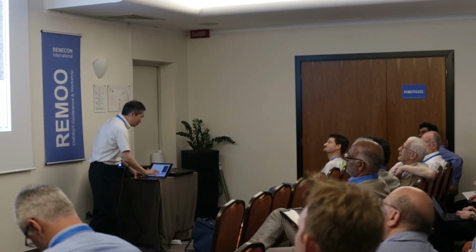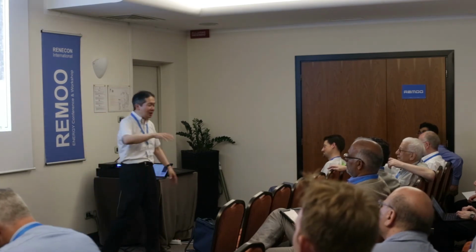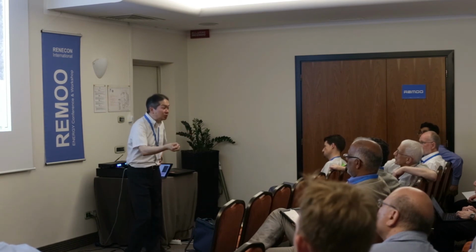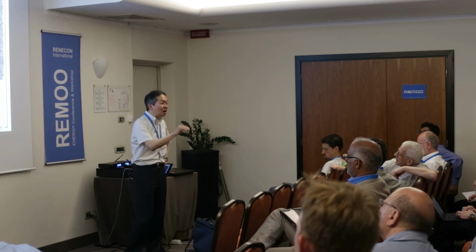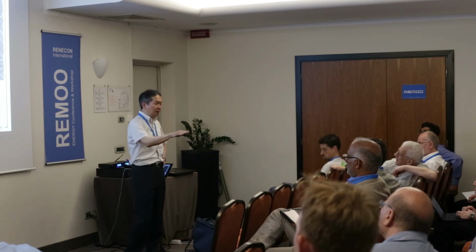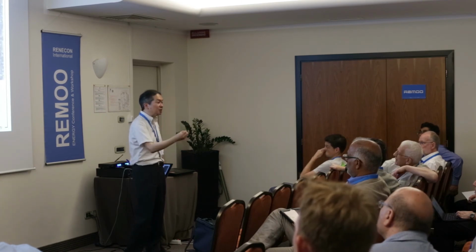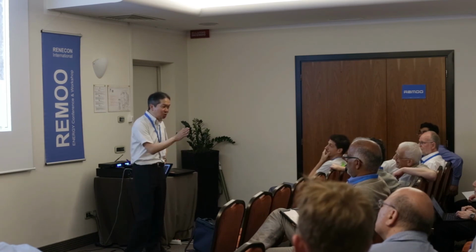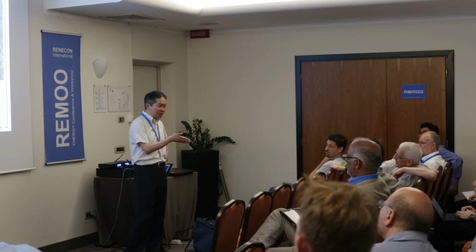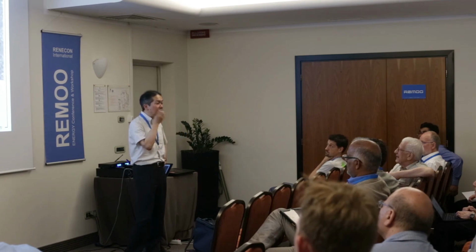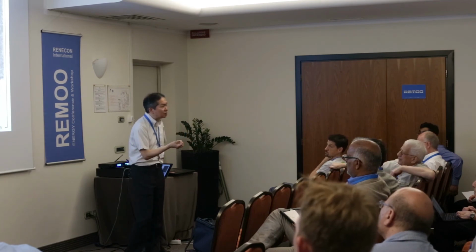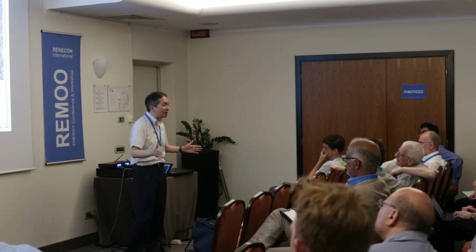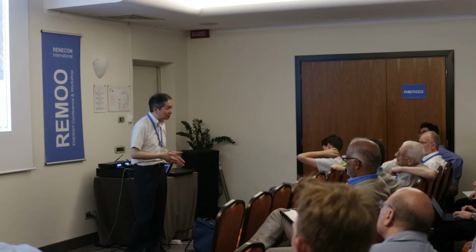It takes some time to go back to that. We don't have time, we'll talk later, because this is an intuitive question. Using the equation of bubble motion and evaluating each term except for the lift coefficient, you can get an answer for the lift coefficient. Sometimes you also have to take into account the virtual mass force and things like that. So without knowing all the terms, you cannot make any evaluation of the lift coefficient.